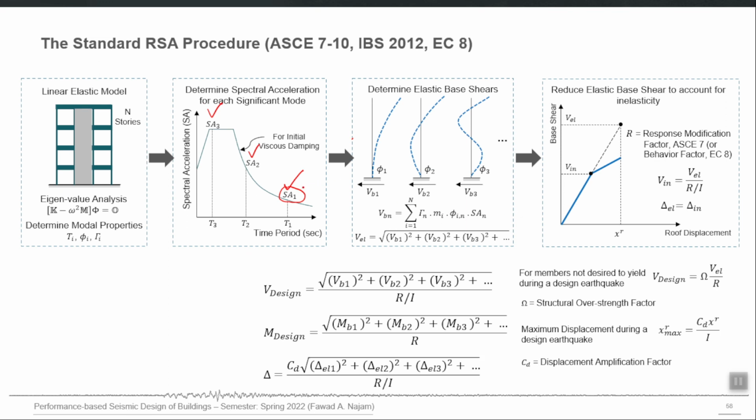So, that spectral acceleration can be multiplied by the mass of the structure, then by the modal participation factor, and then the mode shape itself. This product will give you the total force which your structure is going to experience in that particular mode during the future earthquake, the peak force. Then that peak force can be distributed along the height and applied as loading to calculate the responses corresponding to that mode's contribution, and then we repeat that process for the second mode, third mode, right, and finally calculate the responses. All the responses are then combined to get the approximate peak total response.